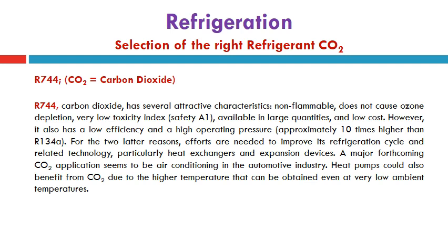R744, CO2, carbon dioxide has several attractive characteristics. Non-flammable, doesn't cause ozone depletion, very low toxicity index, safety class A1, available in large quantities, and low cost. However, it also has a low efficiency and a high operating pressure, approximately 10 times higher than R134a, as can be seen in the solved problem at the end of lecture number 6 presented before.